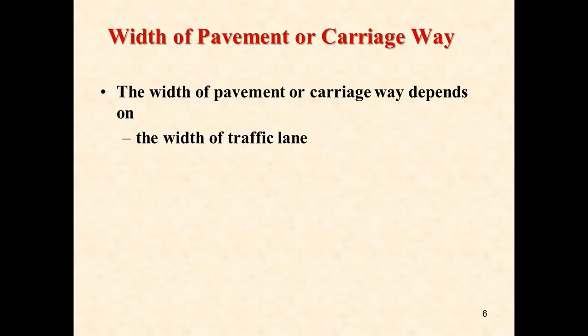What is the width we have to design? For that, first we require how many lanes we are going to provide. Mainly, it depends on the traffic volume. Your carriageway width or width of the pavement is decided by the traffic volume.